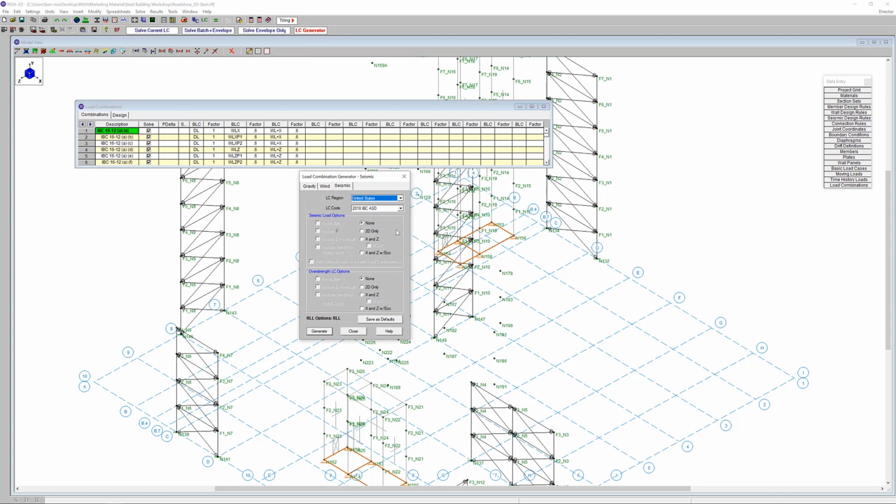We're back on the seismic tab, and I'm going to go ahead and generate the combinations with overstrength and redundancy. So let's say X and Z with eccentricity, X and Z with eccentricity. We'll include the redundancy, and we'll go ahead and include the vertical component. Then maybe we'll include the non-orthogonal if we wanted to. Maybe we don't have to. In this case, I'm going to choose to not include the non-orthogonal cases here. So that's good. We can go ahead and generate again.